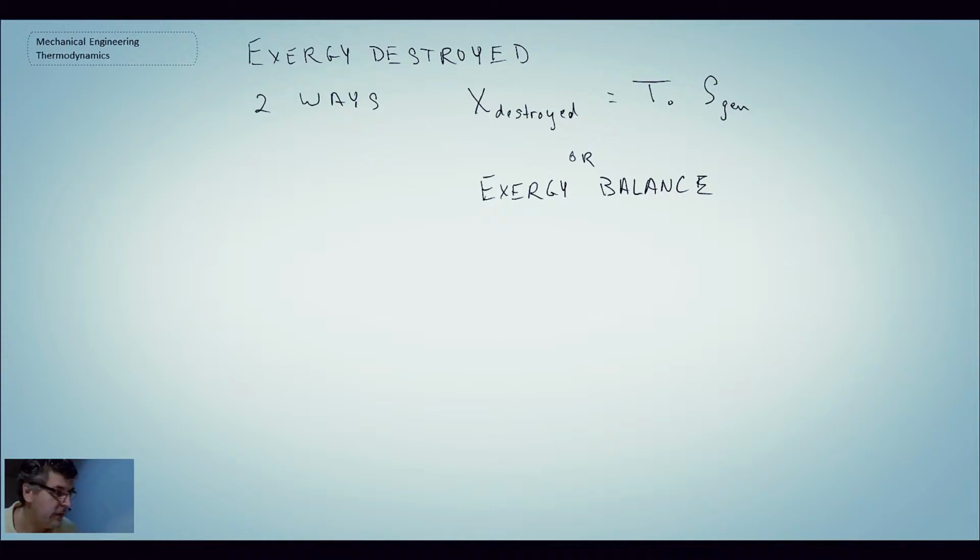So we'll begin here with little exergy destroyed is equal to the surrounding or dead state temperature multiplied by the entropy generation term. So we need to evaluate or calculate entropy generated. So the expression for that is the following.